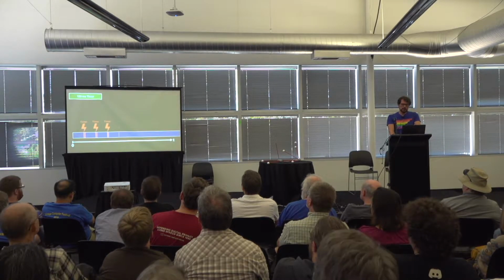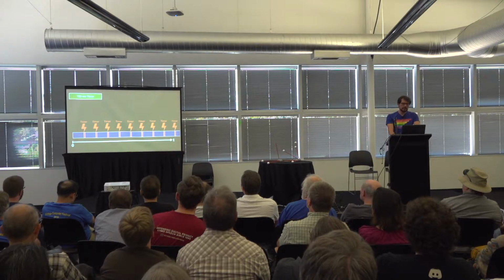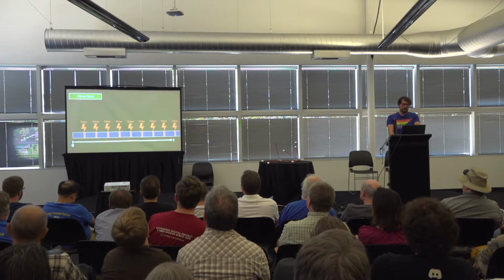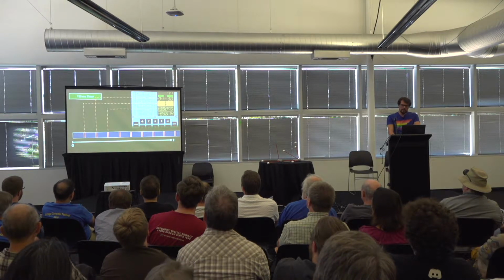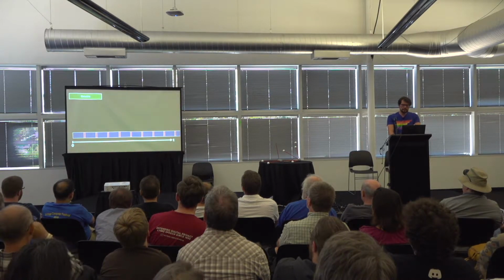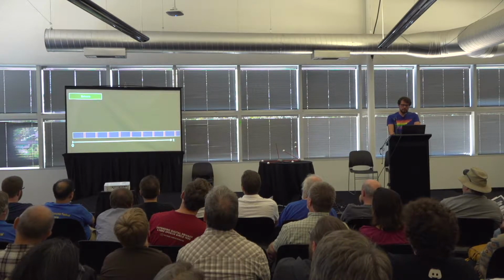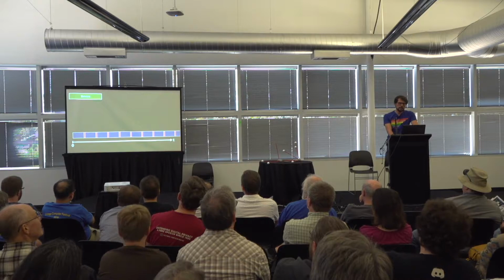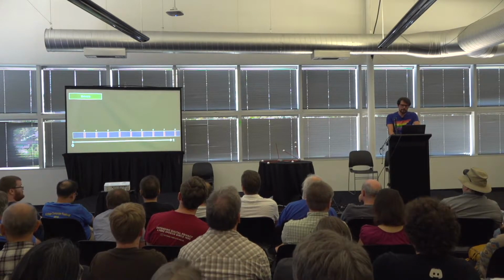A 120 millisecond timer causes interrupts that read data from and write data to certain devices. The numeric display of the DSKY, for example, only allows updating a few digits at a time, so its driver is triggered by the 120 millisecond timer. The timer interrupt cycles through 8 phases, which distributes the device driver across time to minimize the duration of one interrupt handler.